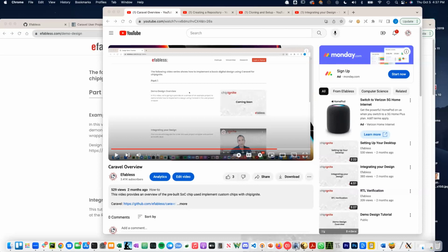There's connections to all the GPIO. There's 38 of those GPIO around the external periphery of the chip. They're all configurable, so they can be configured as digital or analog signals. They can be configured as inputs or outputs or bidirectional signals. And in addition to that, there's a wishbone bus. That's probably the other significant thing you would be interested in or consider in your design. It's available so you can implement a slave device onto that bus, and then you can access that from the RISC-V CPU in the management area. Also provided from the management area is clock and reset, so you can use those as your source for clock and reset for your design.